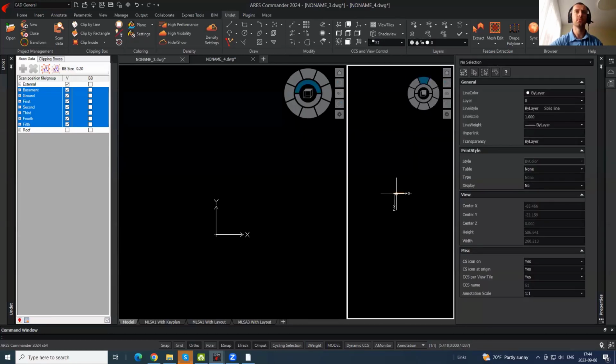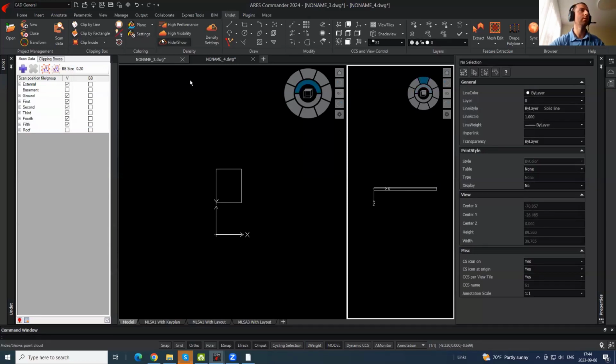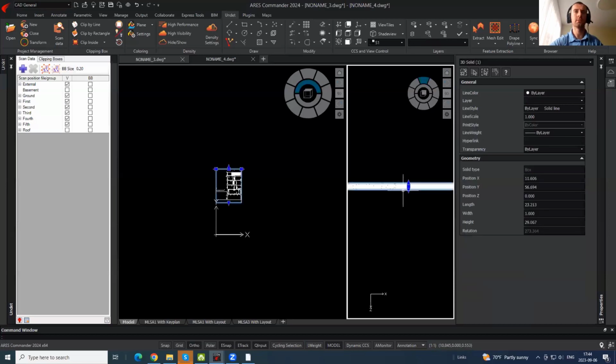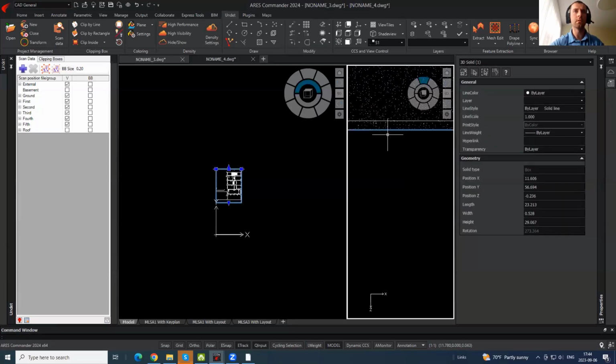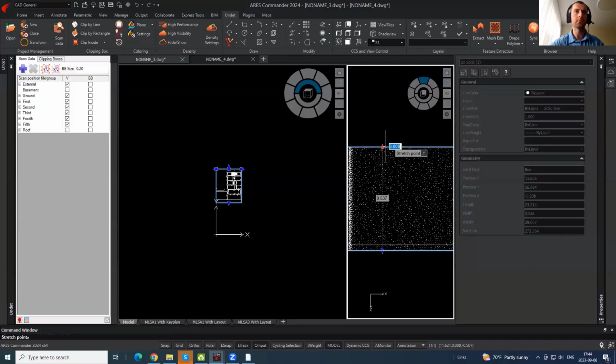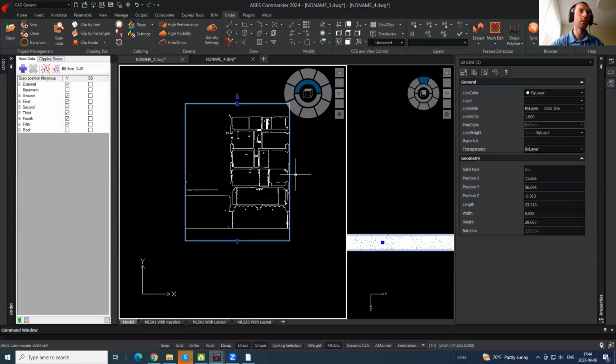So we have this type of axis. Let's clip our point cloud by line, by this section line, and see what we have. Let's make it thinner to have only the section plane lines.